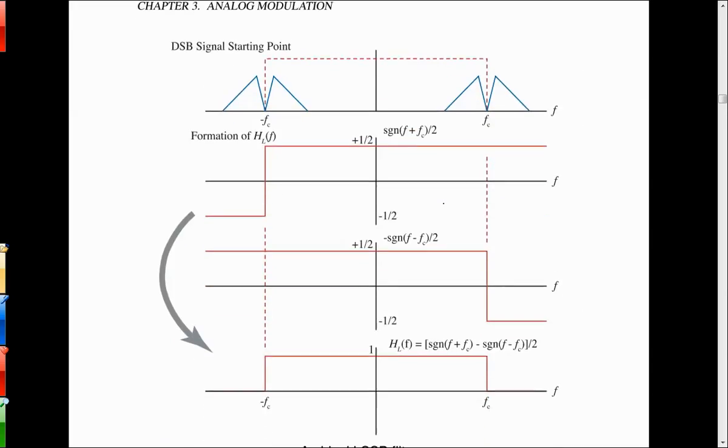So I've got a kind of graphical approach to getting the solution here. The graphical approach starts by saying, okay, here's my two-sided spectrum of double sideband. If I'm going to go after the lower single sideband, so it's called LSSB, what I'd like to do is come up with an effective filter, that red dashed line, so that the signal can go through this filter, and all that's going to come out is the lower sideband. Does that make sense?